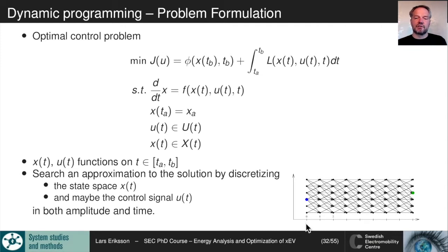The state of charge can be empty and up to full, and then we have selected a number of discretization points in between, and then we're looking at how this state evolves over time. In a hybrid electric vehicle, we are free to use this during our driving. So this is an example of where we're using one of the free dimensions to find a better solution than just using the traditional vehicle. With a hybrid electric vehicle, we have one more free dimension. We can utilize the energy storage to shuffle energy from some points to other points, and we can use that degree of freedom to gain fuel economy.